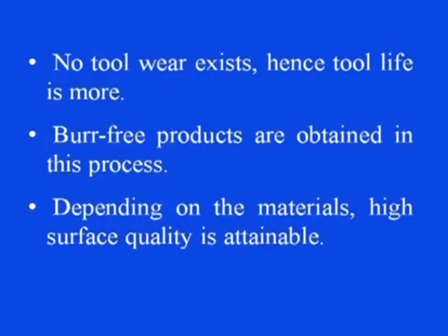Being a chemical process, even a material harder than the tool can be very easily machined, and this does not affect the MRR, which is very unique in this case in comparison to conventional machining processes. Complex shapes can be machined on hard materials. No tool wear exists, hence no tool life problems. Burr-free products are obtained in this process. In fact, this process can be used for removing burrs. Depending on the materials, high surface quality is also attainable.